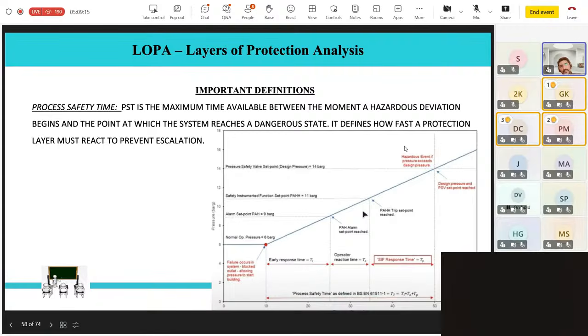Their chemistry department was meticulously calculating the response time for any runaway reaction going from the operating envelope to the hazardous condition, because they want to prevent any release, since even a small release is catastrophic in case of hydrogen cyanide or other hazardous chemicals like an H2S release, chlorine release or ammonia release. So in such cases, they have to meticulously calculate this time based on process chemistry.